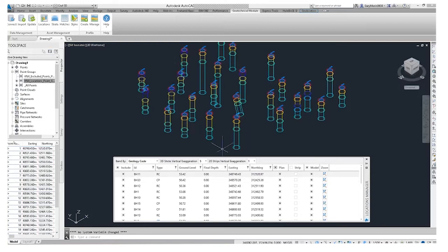So moving on with this though, what we've got here is that we can display certain borings. We can also use this include one over here. I mentioned you can decide whether you want to include a boring or not as you import. Perhaps you didn't notice that one of them has got some very odd results going on with it and you prefer not to use it.